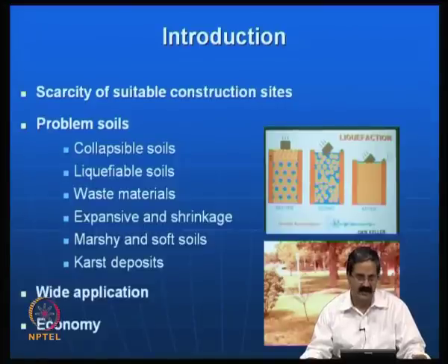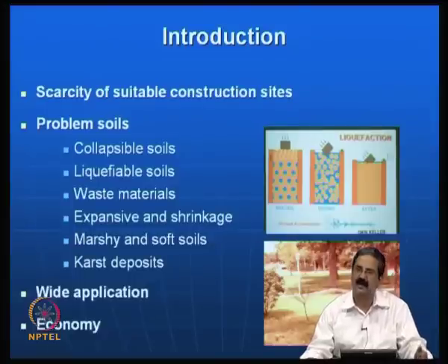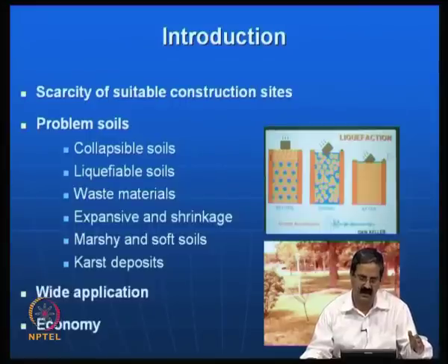These collapsible soils are nothing but the soils which have a tendency to collapse upon loading. Many reasons, such as the stable or unstable metastructure or capillary stresses nullification, are some of the reasons for this collapsible nature of the soil. Suppose the soil is partly saturated, and when it comes in contact with water, all the capillary stresses are destroyed, and because of this there is a volume change. It is in fact a reduction in volume, and that leads to collapse.